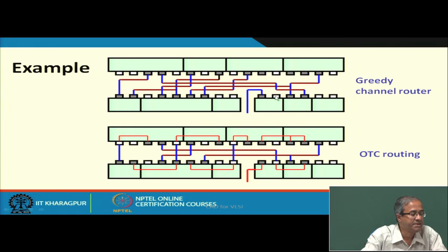Type 2 means there are some vacant blank terminals in between. So, instead of starting from here and going like this, you do an over the cell routing here, come here, over the cell routing here, come here. You will find that this reduces congestion in the net, in the sense that you can take a straight segment and connect to it. So, in this way you identify all type 1 and type 2 connections, but again do not blindly use OTC routing for all of them. You use them only if it reduces the channel congestion with respect to some cost metric.